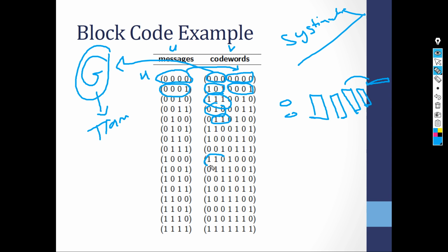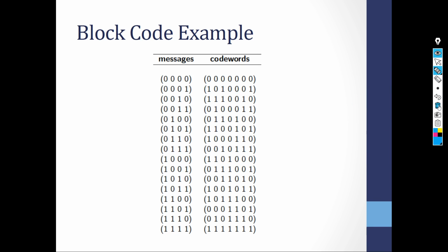Because here, for example, the message, this one is basically this one, exactly. And the other bits, those ones, we call them parity bits. Why do we add these bits and how do we obtain them? Using a generator matrix, like a transform matrix that depends on the input and independent basis functions. And what are these bits? Parity. How do we use them? We use them to detect if there are errors on the message signal. This is how the block code basically works.